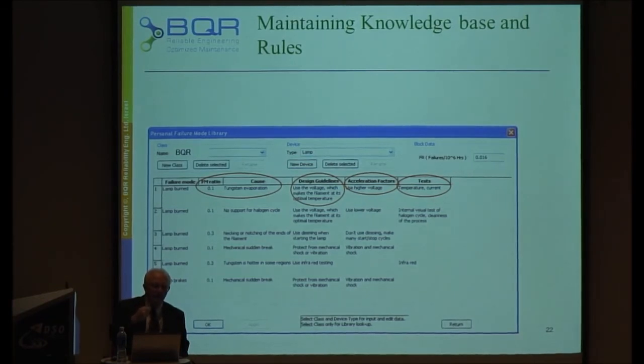So if you do that fast, you can harm the bearing. If you do that slowly, it warms up, everything is okay, and you don't get any failure. So there should be some design guidelines when you do a design, and this is coming from the FMECA. In this case, one of the rules, the design guidelines, is to use a dimmer in such lamps.